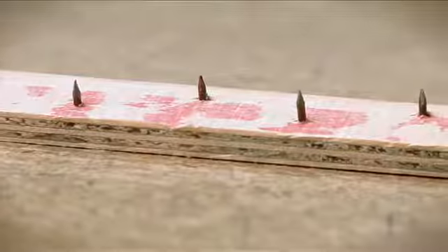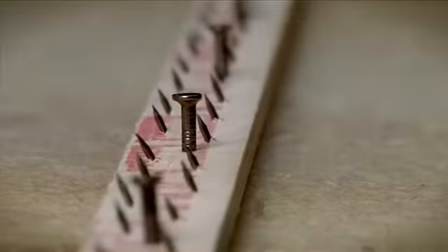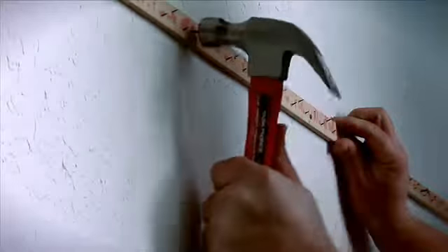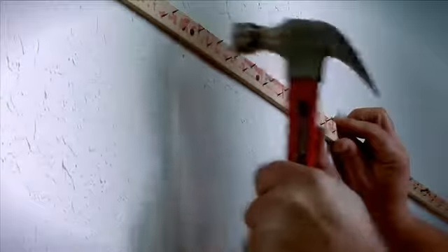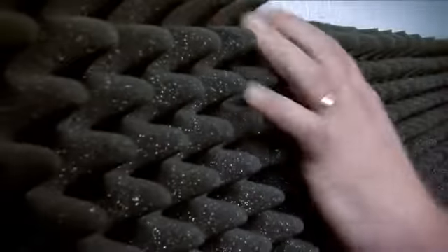If you're looking for quick, easy alternatives, try hanging cheap furniture blankets on C-stands or using them to cover bare floors. Another inexpensive and simple method for removable installation of acoustic foam is carpet tack. Carpet tack is a 4-foot strip of wood studded with small nails that's used in the installation of wall-to-wall carpeting. Carpet tack is readily available at your local home improvement store. A horizontal length of carpet tack mounted to a wall can be used to hang acoustic foam. This same method also works great for hanging rugs for decoration and/or sound dampening.